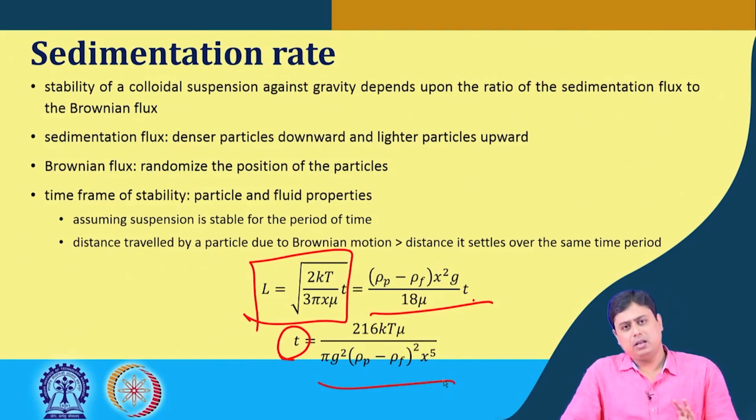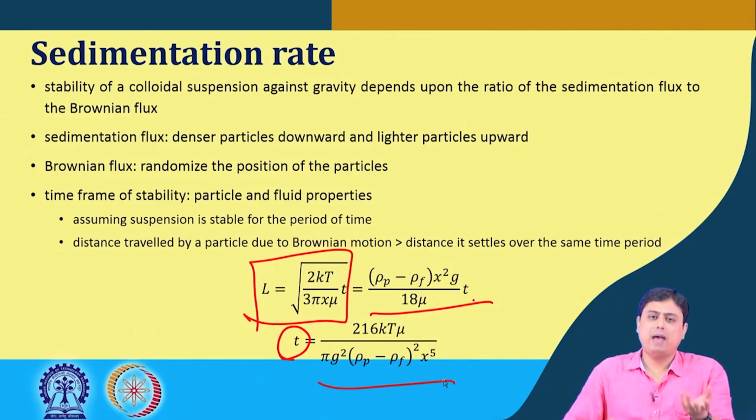So, that means if we provide sufficient time, all the suspension will settle. But the logical question is, what is the time frame? We cannot have months to work in a sedimentation tank. We cannot provide a month in a sedimentation tank or a thickener to have the particles settled. It has to be in the order of hours.